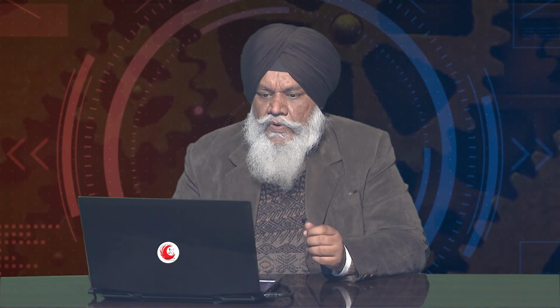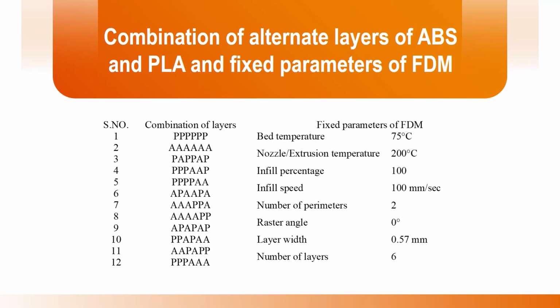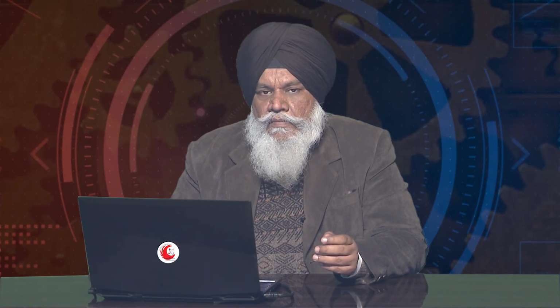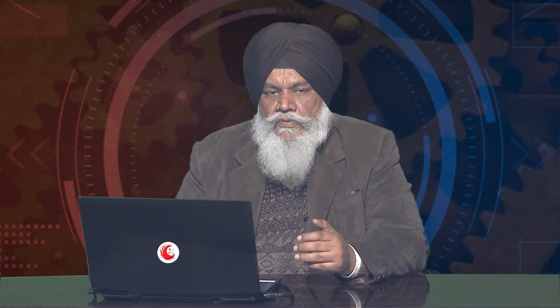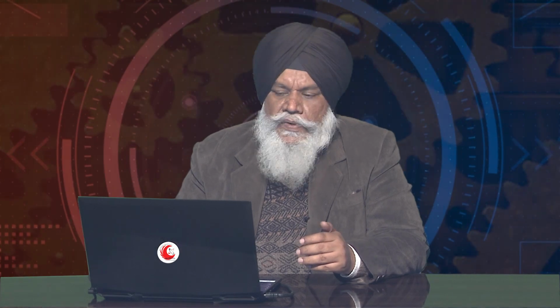Let us see one of the important considerations. For this work, some of the parameters have been kept fixed, and only the layer combination has been changed on an open source FDM. Here I just want to remind that FDM, FFF, and material extrusion are overlapping words. FDM is of course a patented technology, but after 2018 the patent is over, so most researchers take it as fused filament fabrication, and as per the recent code given by ASME and ASTM, it has been categorized as the material extrusion process. So these are repeatable words, right?